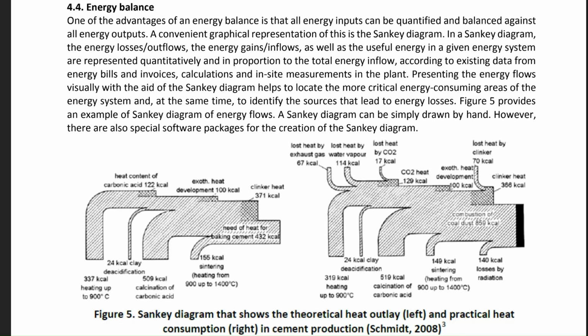So that is to be specified. That is to be nominated, described earlier, what scale you are taking, that is more important. For example, if you are taking these 24 kilocalories as 1 mm, then if we are drawing any other, say 120 kilocalories, it will be 5 mm. So those dimensions are important. Here in the Sankey diagram we cannot draw the width of the inlays or outlays, input or output, inflows, outflows in a random manner. We cannot do that. So that is to be specified for both the diagrams.